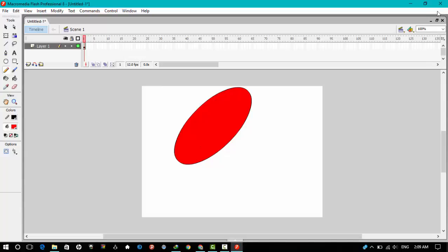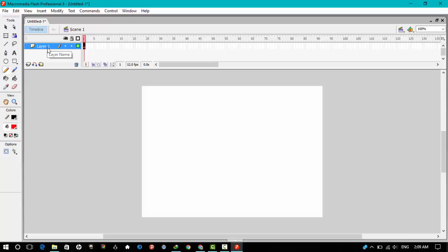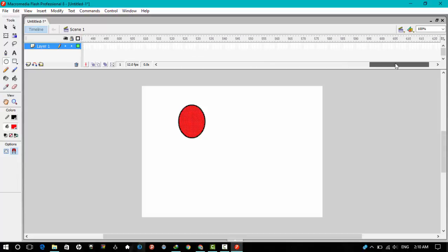And the next thing is the timeline. This is a major part of Flash. So I'm going to remove all of this mess right here. I'm basically in my timeline window. My timeline window consists of my project name along with the layer I'm in. If I create a circle right over here, that's in layer 1. This is basically a time span. I've got frames 1 to 635.